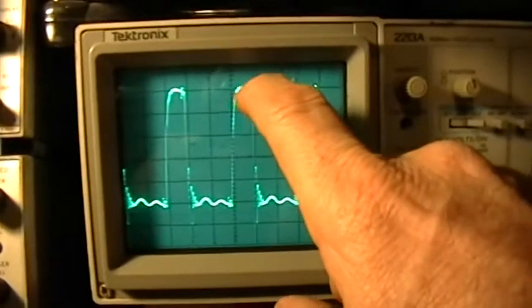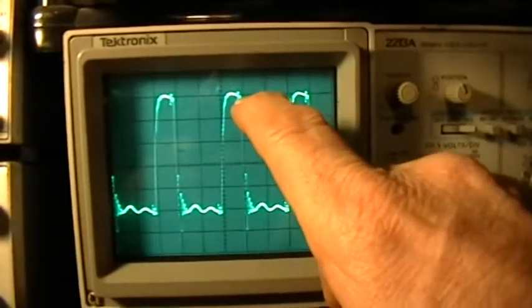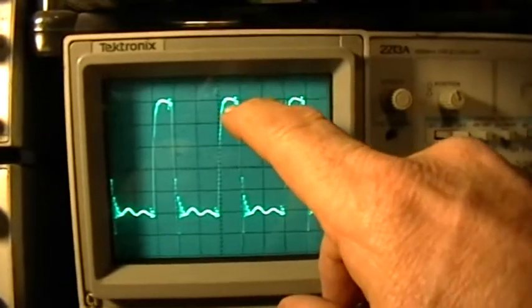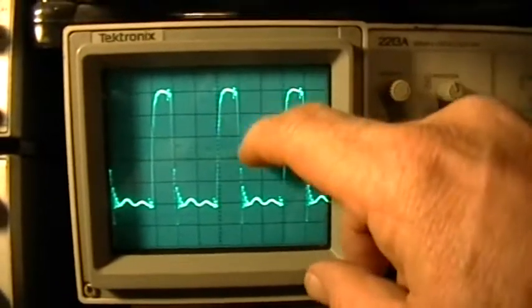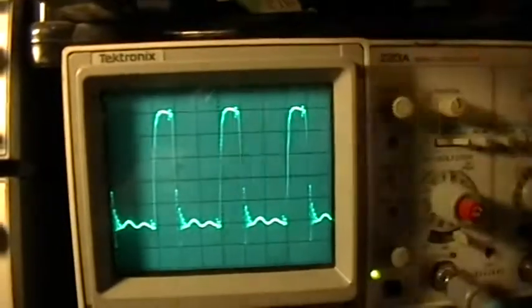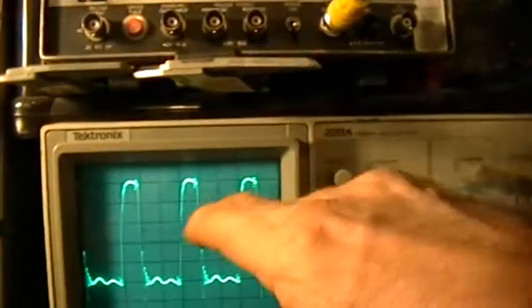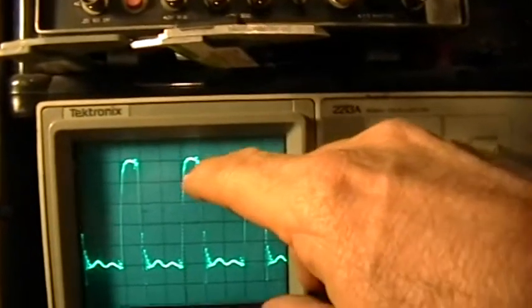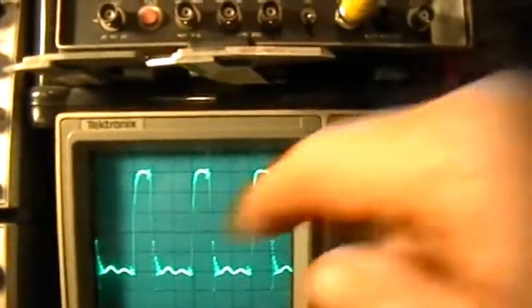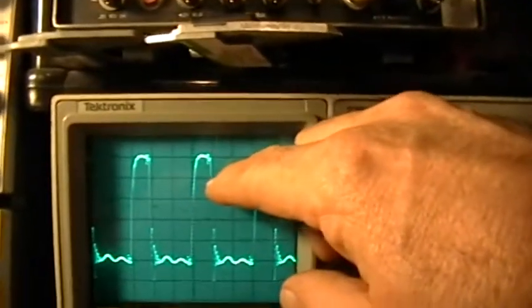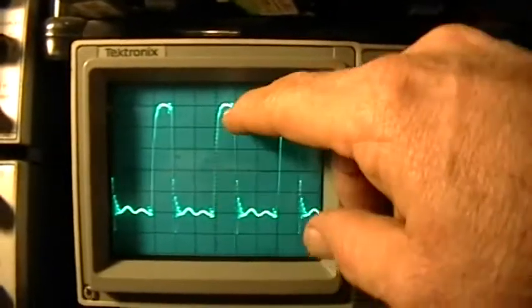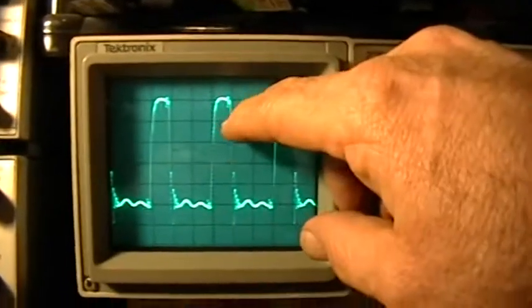So if you cut off that 5/10 of a volt, the top area there, and then fill in the shoulders there, you're probably going to wind up with about 0.45 volts of drop across the 0.25 ohm current sensing resistor.